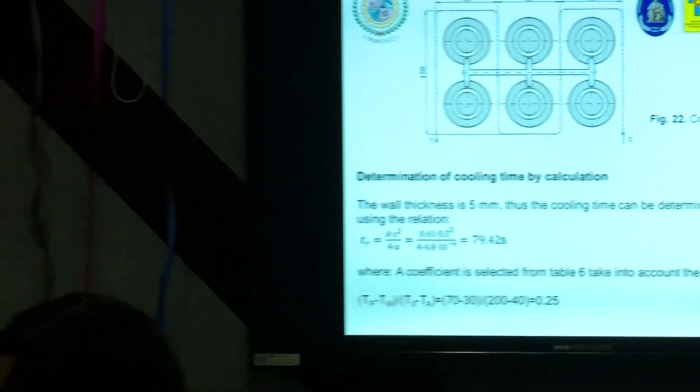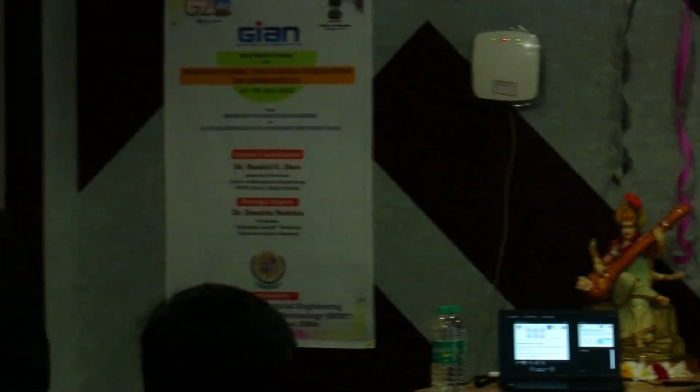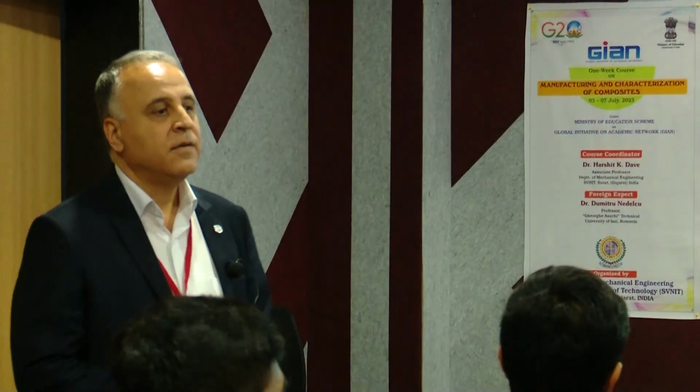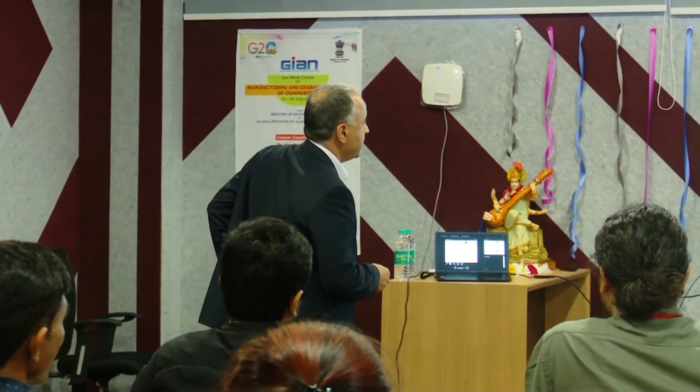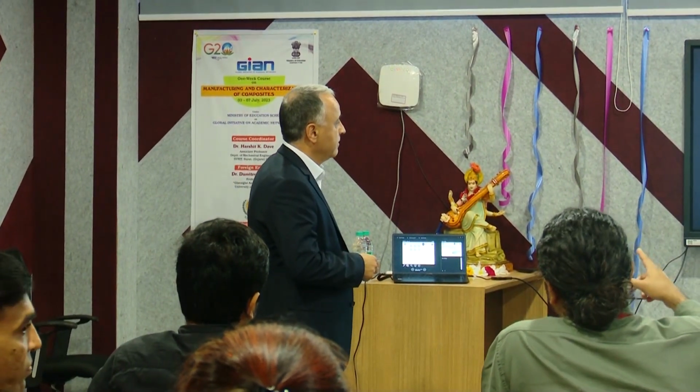That's why the diameter of the cooling pipe and the quantity of liquid fluid flowing also matter in this case. Then you can maintain a uniform temperature. I think those calculations are for this type. There was a slide where an 11 mm diameter was given for the cooling channel.